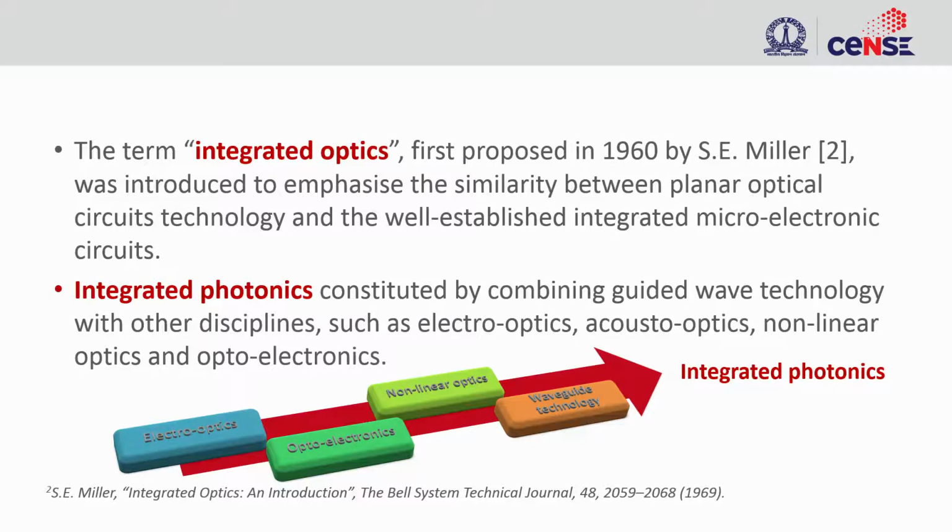That was the initial proposal, and now what we understand as integrated photonics combines a guided wave system. The various components that we had on the optical table had no waveguide, no guiding mechanism. This is all free space. Light was traveling in free space since we were using coherent light sources, so there was no divergence and you were able to manage it. So, there were no waveguides. In case of putting a circuit on a substrate, you need to have a guiding mechanism.